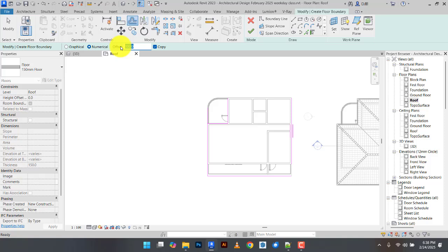Very small. But our block wall will fall on that same slab. Our block wall, the outside one, and the parapet wall, and then the upstand, they all fall on that slab. So 1,200, so that you have enough space to walk around.